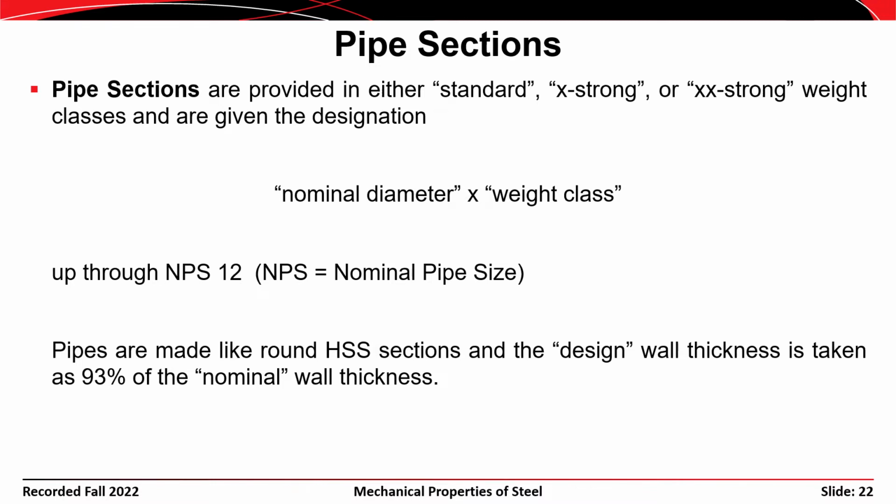But typically the HSS member is going to be a better steel. They're rolled to different tolerances and things of that nature. So pipes are fine in a lot of cases, used as a post, maybe in a small building, but an HSS is fundamentally just a better steel and a better member.